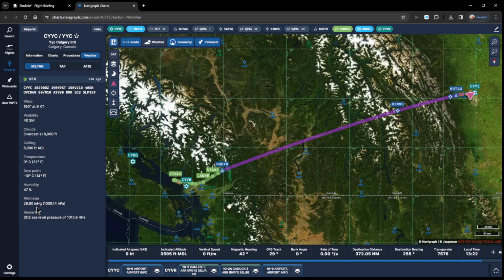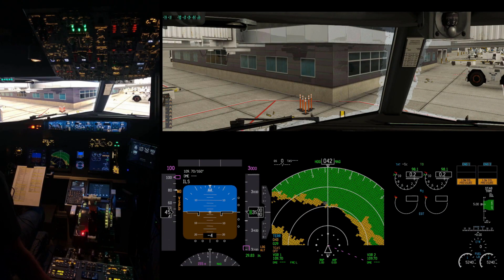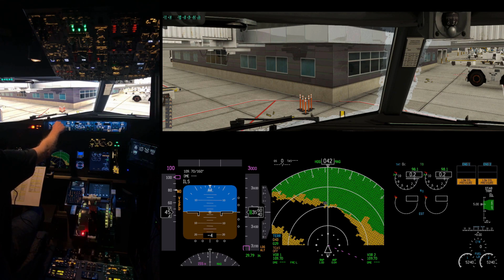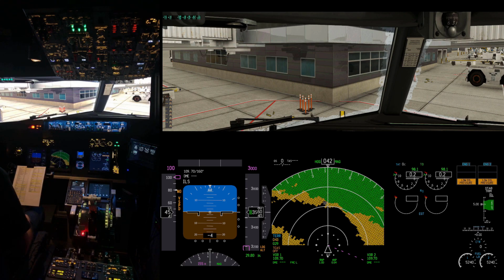So we're going to switch over to the flight display and show us adjusting the altimeter to have the appropriate altimeter setting for our altitude for takeoff. So switching over, now you can see our PFD in the middle, shows our attitude. You can see at the moment our altimeter is set to 2983, and it's actually 2980, so we're going to adjust that down using the EFIS on the main instrument panel to 2980. Okay, 3560, that's the elevation of the airport, so we're good.